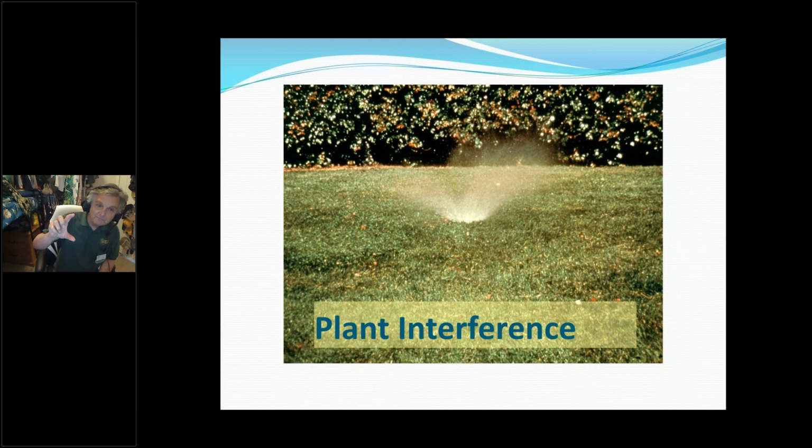If you only have a 3-inch pop-up sprinkler, it's barely going to get over the top of the lawn that is there around the sprinklers. That's why 4-inch sprinklers are pretty much the standard now, so they can pop up and over a 3.5-inch tall fescue lawn. Otherwise, you're going to get an awful lot of water right there near the sprinkler and not too much elsewhere. Next.